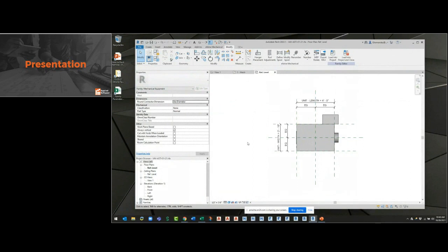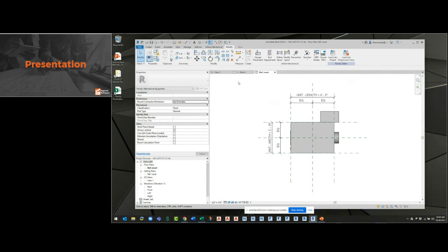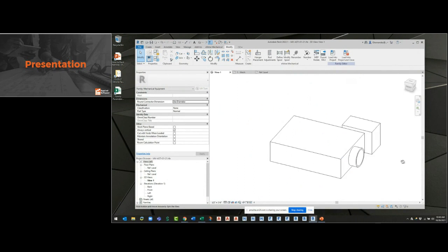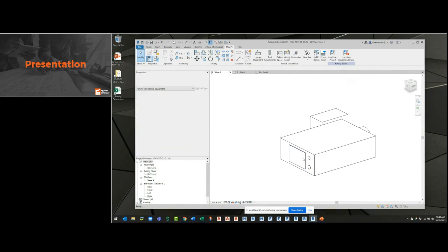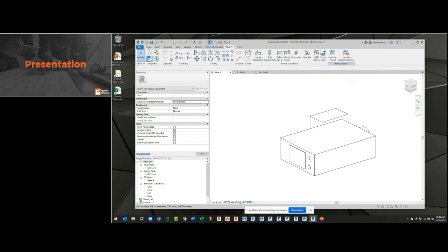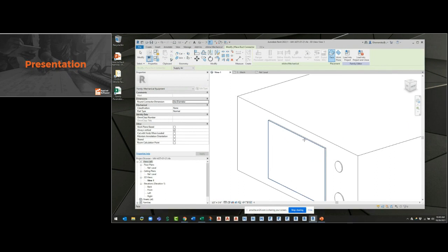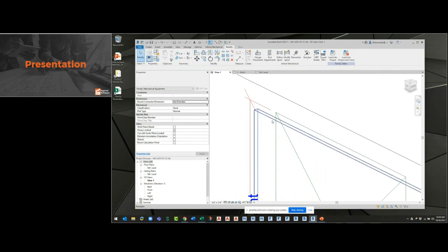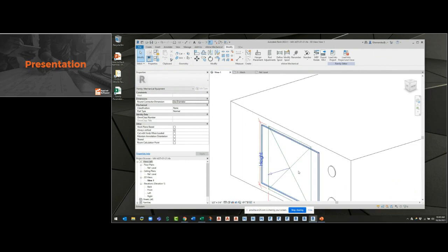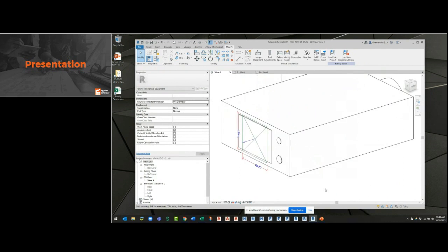Okay, got a little bit of time left here. Now, the last couple things that I need to do here in order for this to work is to make this MEP, right? So this is, again, the reason why I did these little tap outs or the extra geometry. This panel right here called the connectors, we've got electrical connectors, duct connectors, and pipe connectors that we're going to worry about, right? And I'll put in a duct connector and I'll place it right here. And this is, again, why I place it on the edge of that surface. So it's going to be sticking out on the outside lip there, right? But it's still not in the right shape, but that's okay for now.